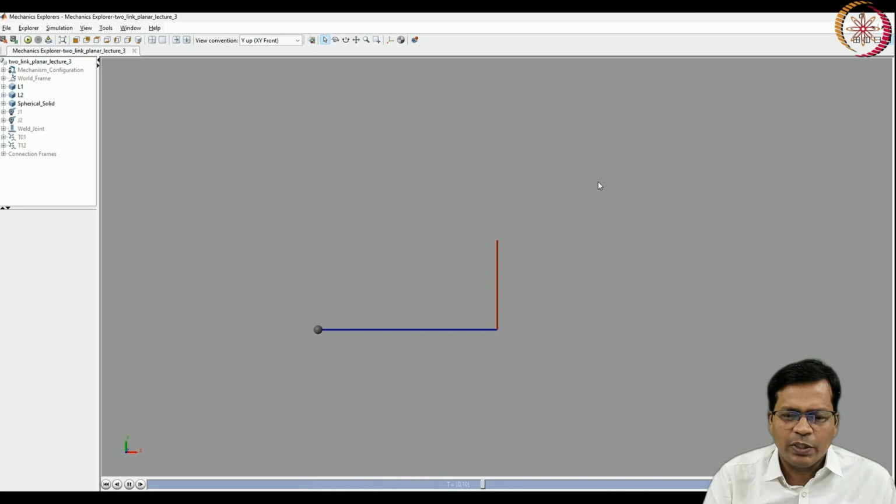It is not moving because torque is not varying, and it is controlled by the torque. So torque was sent as an input and motion was calculated automatically. When you feed in this gravity torque to the joints for minus pi by 2 and minus pi by 2 for joint angle 1 and angle 2 respectively, it holds the robot in this particular pose.